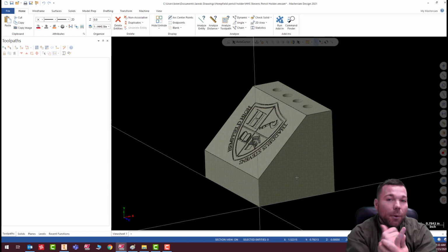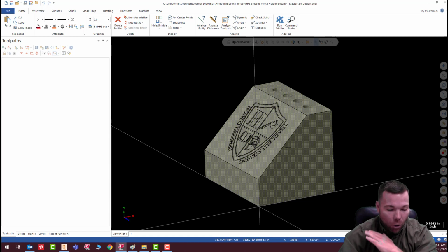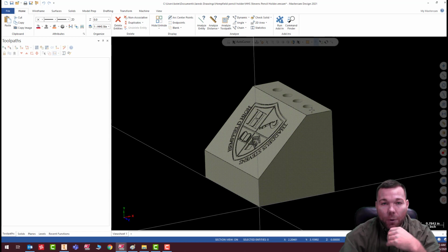Well, we said we wanted it to look aesthetically pleasing, right? That's the whole point. It's a showpiece. So that means that I want to mill all sides of this. I want to make all sides shiny, milled face. It needs to look good. So that's why I need to use larger material, which also tells us how we're going to manufacture it.